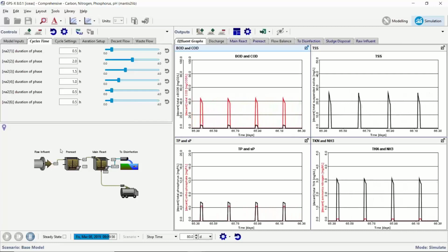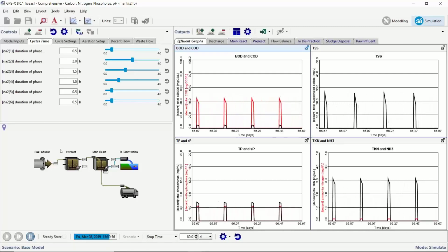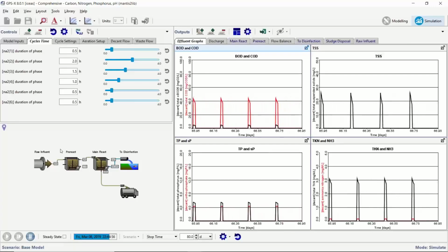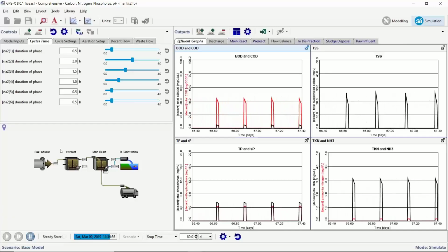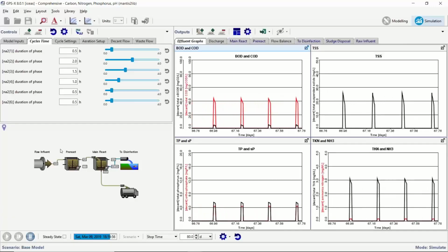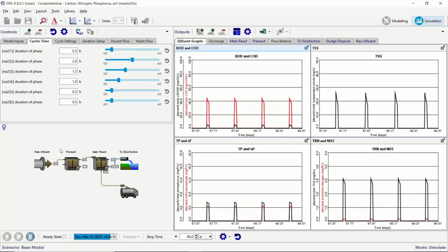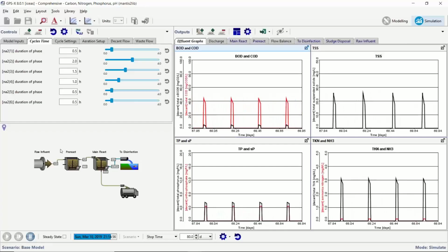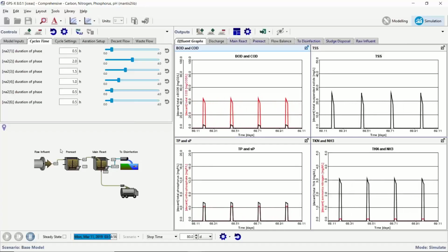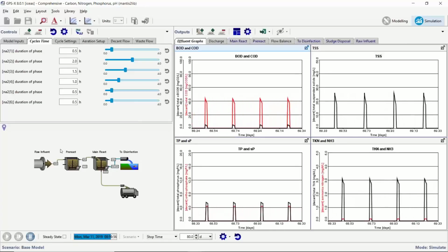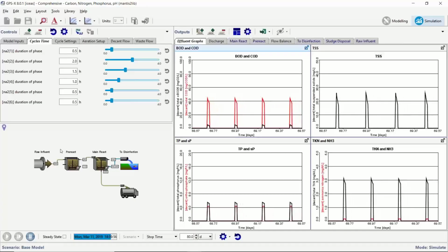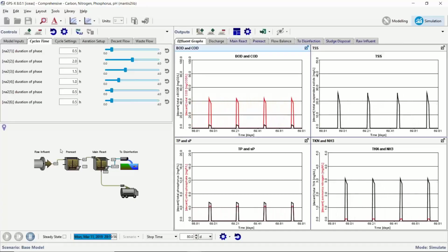So for example, during the period when my colleague Dan and I were putting this together, and I should thank Dan for doing a good job of putting all these examples together for me, we spent a little time fine-tuning the effluent solids. We noticed they were a little bit high, so we shaved a little time off the aeration because otherwise it was nitrifying fine and BOD was fine. And we added that to the phase to allow for more settling so that the effluent solids would be lower.